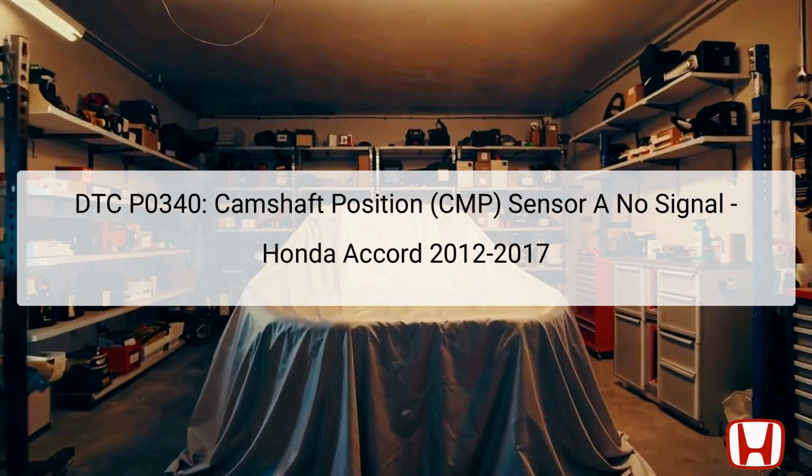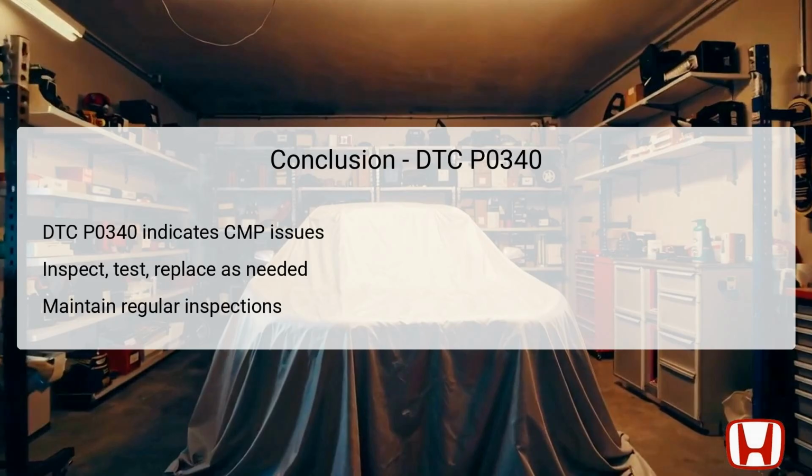Understanding the function of the CMP sensor within the broader context of engine management is vital for diagnosing this error. In summary, DTC P0340 signifies a serious issue related to the camshaft position sensor A not sending signals to the PCM. Understanding its role is vital for diagnosing any potential problems effectively.